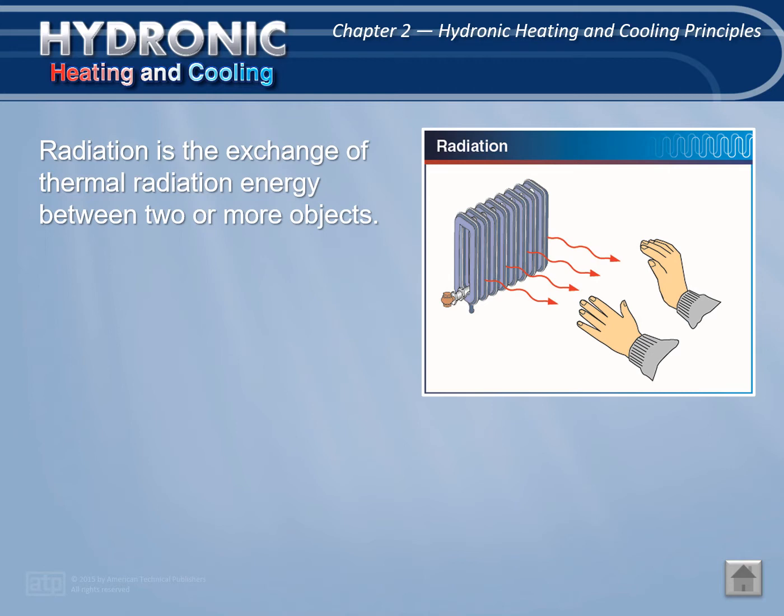Whether the radiation results in the body gaining or losing heat, the rate at which the gain or loss occurs depends on the difference between the temperature of the body surfaces, or bare skin and clothing, and the overall average of the temperature of the surroundings. The overall average temperature of surrounding surfaces is called the mean radiant temperature.